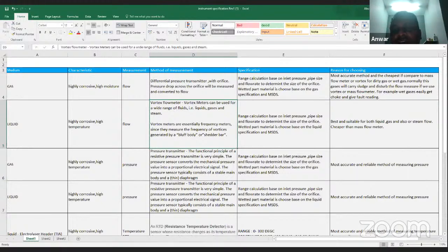Yes, it can be done, but it requires proper process assessment and also risk assessment to be conducted, because it will impact the downstream and upstream of the process when you take out the equipment for offline calibration.